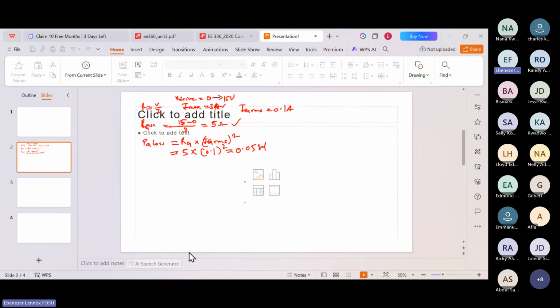So we can make this the subject, right? If you do that, you're going to get 15 e exponent minus t over RC to be equal to 15 minus 5. So you can divide through by 15, right? That gives you e exponent minus t over RC to be equal to, sorry, this is 5, to be equal to 10 over 15, and this is 2 over 3.